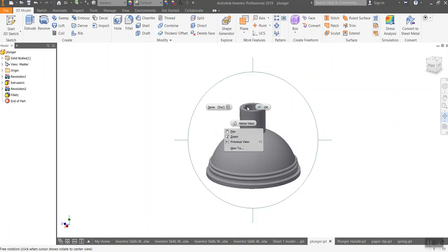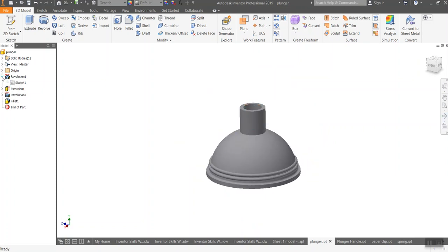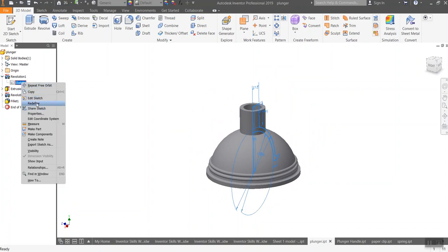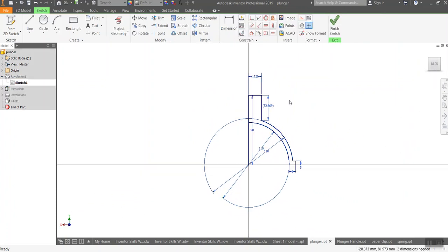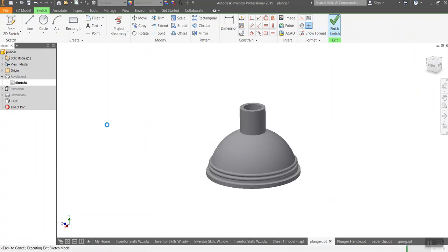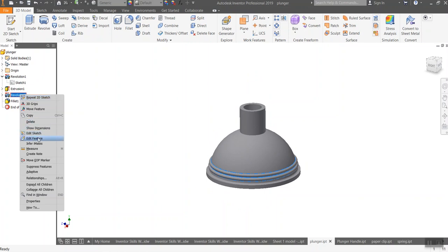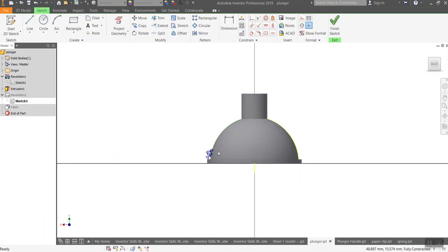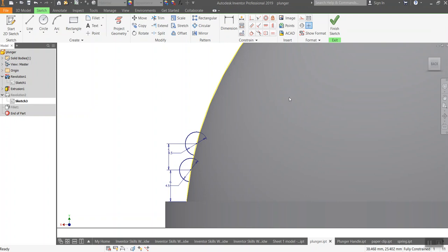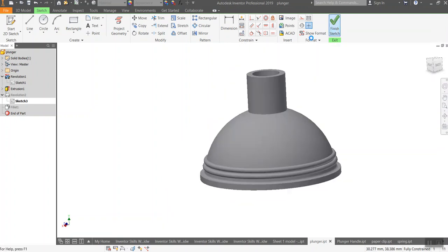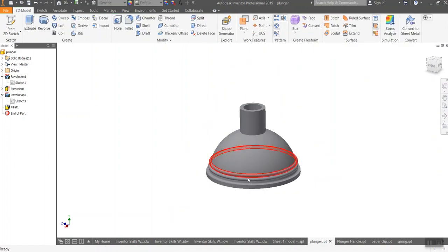It's round in shape. So what we're looking at doing is using a revolve. If I show you the initial sketch that I did, quite a complex looking sketch again, using curves, etc., using dimensions, revolving it about this axis to create the shape. And then after that, going in and adding an additional sketch of these 2 little semicircles, and again revolving them around the shape to create the finished object.